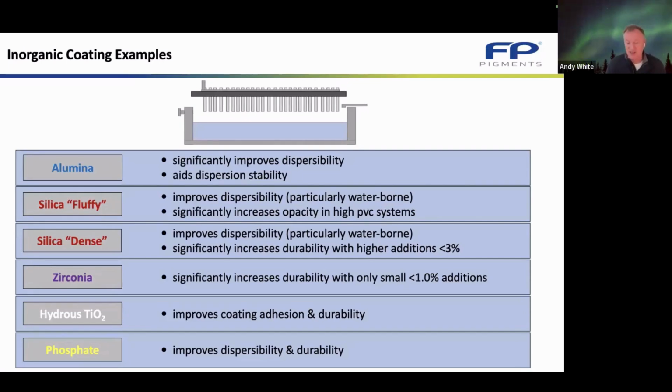Aluminium oxide has 9 different crystal forms that have radically different shapes and sizes. And the titanium dioxide manufacturers over about 50 years have developed a finesse in the use of these different types of alumina to change the nature of the surface of the TiO2 and therefore how it behaves.